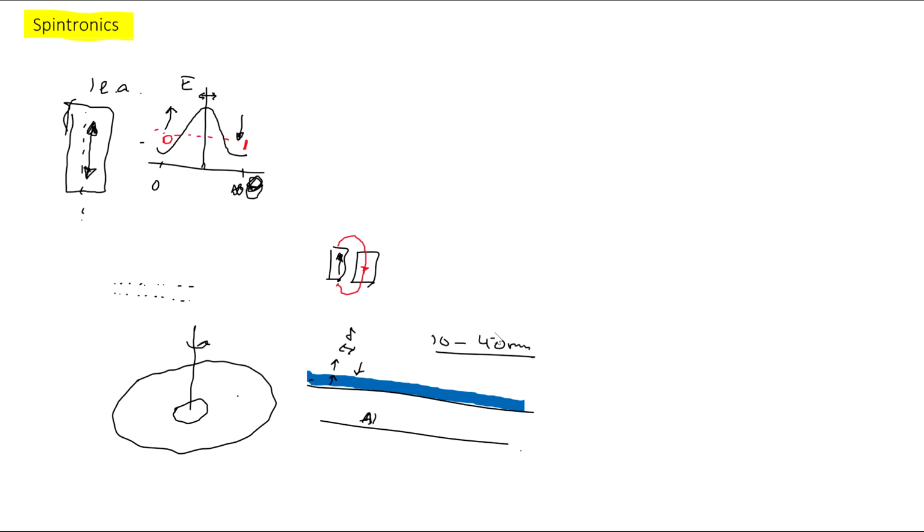So this is the limit. In order to reach that limit, we have to be able to apply local magnetic field, because if you want to write the information in this area, you have to apply magnetic field that is, let's say, pointing up, but it is very strong in this area and it falls off very rapidly to the sides, which means that it has to be concentrated. And also you have to be able to read this magnetic field, because magnetic field produced by this domain, it goes, as you see, it goes up.